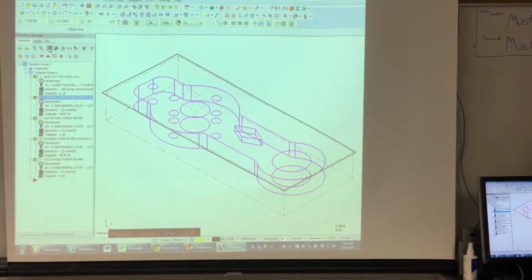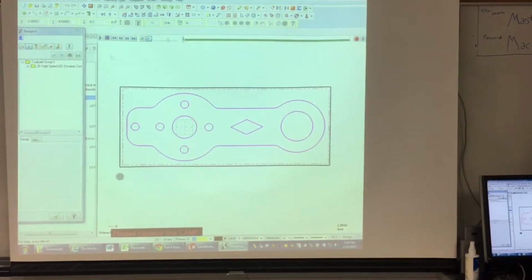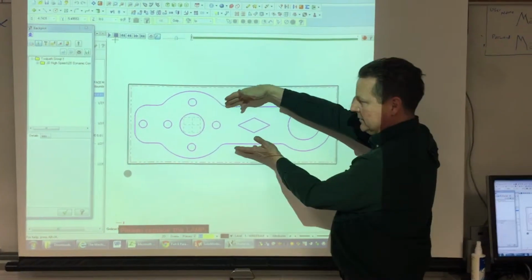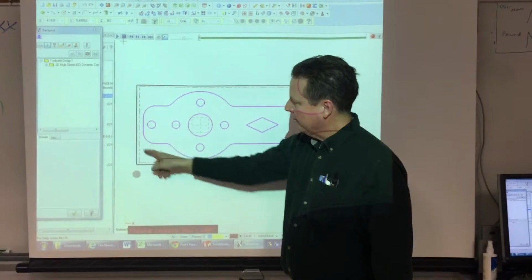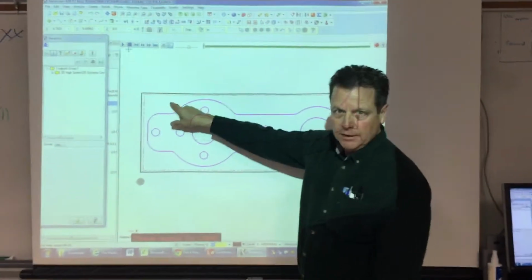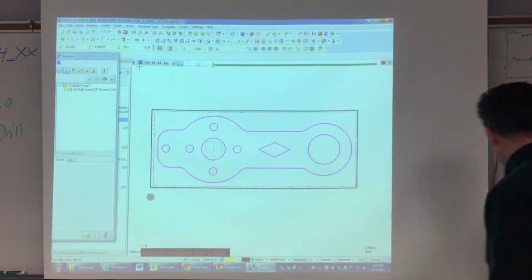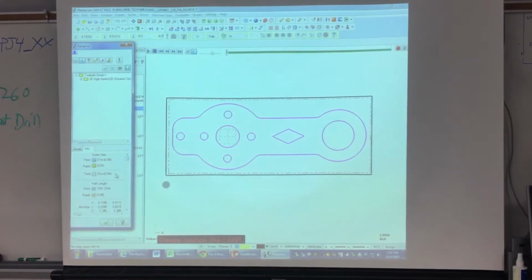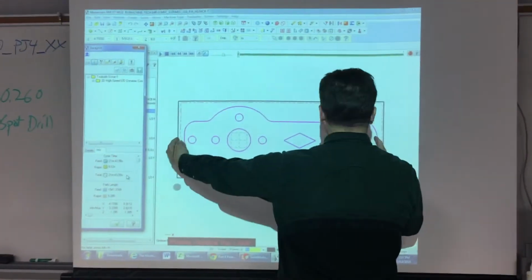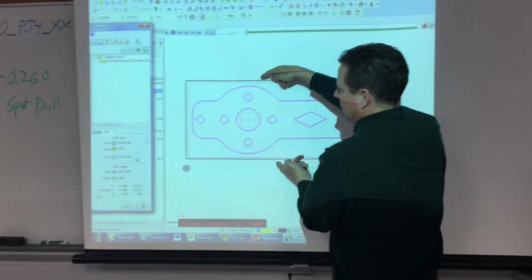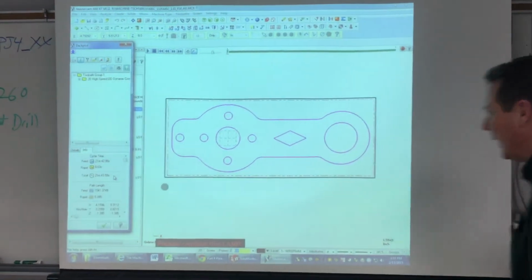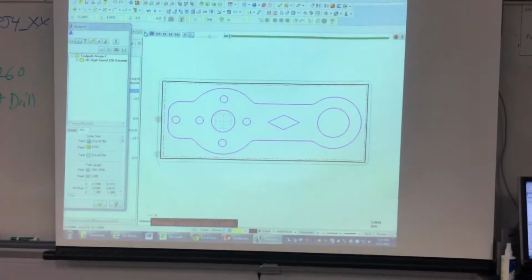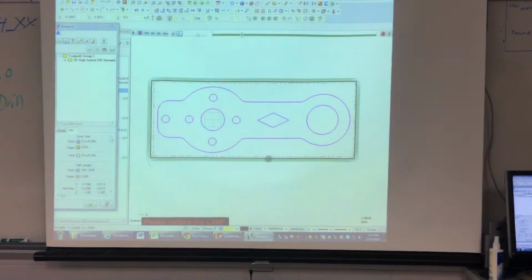And then I proved with a back plot, we watch from the top here. This is the outer ranch fence. This is the ranch. Mastercam will pick the best way, always climb milling, to get rid of all this area. So watch carefully. The toolpath says it's going to take 21 minutes. This part is in actuality 12 3/4 of an inch long, 3.5 inches wide. Pretty big part, relatively. And we watched it all this time.